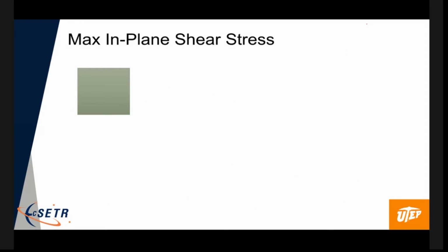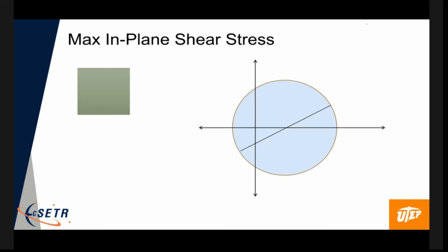And let me just do one last bit. Max shear, same point, right? This is the same thing, right? So it's Mohr circle, right? What about this point where we're up and down, okay? This is the point where we have the max in plane shear.